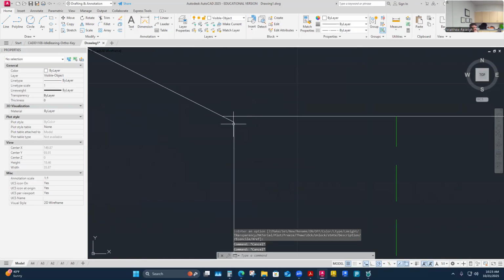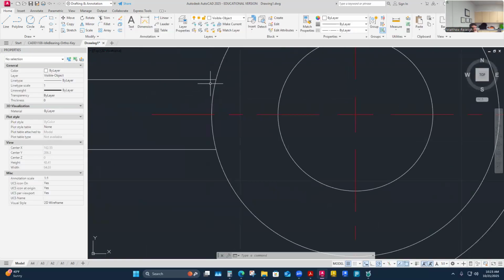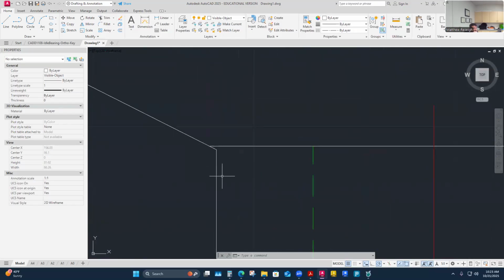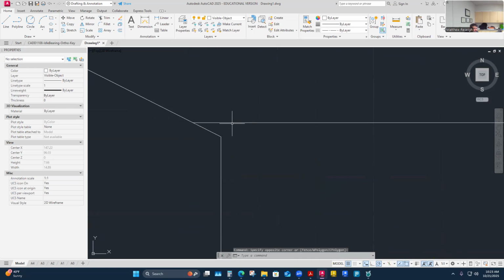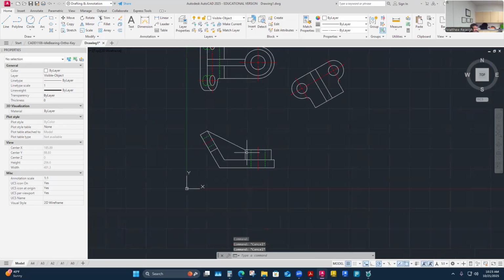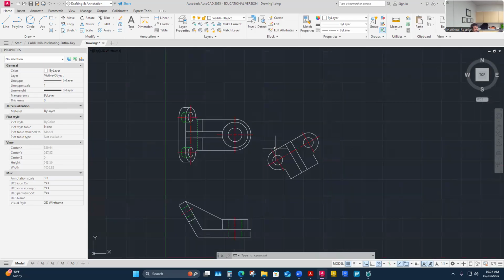Yeah, and technically that surface probably has to be contoured like this, huh? That gusset actually has to be either milled out or something, to put this contour in the shape of that part in order for it to match that. Yeah, that's a good catch. It's a little bit weird going on there. It's a little bit more complicated. If I'm truly keeping this surface flat, yeah, this is correct, huh? But because I need this overall diameter still. Yeah, good. That's a good catch. I don't think I've caught it before. I don't think my drawing currently, if I pull that up, has that detail in there. That's good.